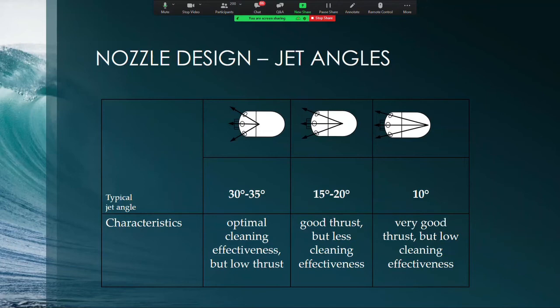So it could be a two-pronged attack. I could go in with the regular nozzle, get most of the stuff out, then go in and polish and finish up with the other nozzle, and then I'm out of here. Like we said earlier, any debris left behind, be it struvite or grease or anything else, is the beginning of your next blockage. If you can get it gone, that will extend your cleaning periods.